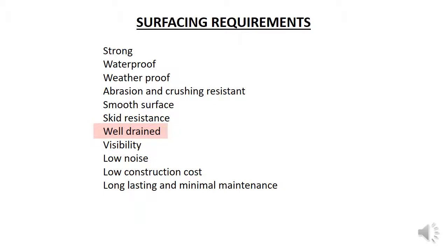Water on the road surface reduces the contact between the vehicle and the road, increasing the risk of vehicles aquaplaning in wet weather. The surfacing needs to be designed to be able to maintain contact between tyres and the road in all rain conditions. This means the road is designed to drain the water off the road using cambers or porous layers and have surfaces that remain above the surface water level. We will see how chip seal surfaces are designed so that the water drains in the low parts of the chip, but the chip still protrudes out of the water to provide grip for the vehicle tyres.